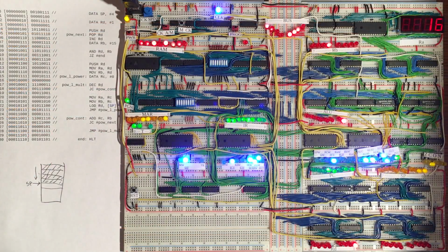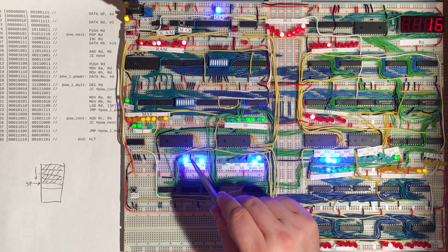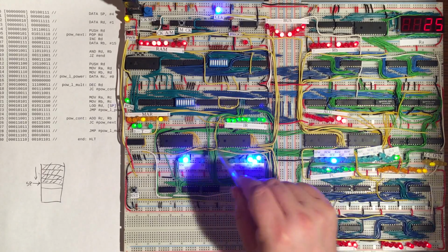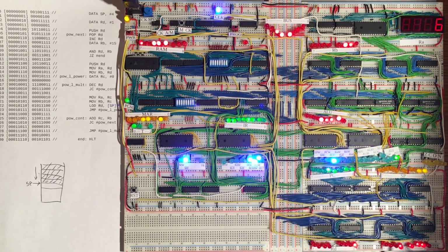And so with that, I think we've now completed our tour of this CPU. We had a look at the microcode of all the instructions that we currently support, and the program which writes that microcode into these EEPROMs. And then we also looked at the hardware of the control unit here, which is sending out control signals to the computer on all of these yellow wires.